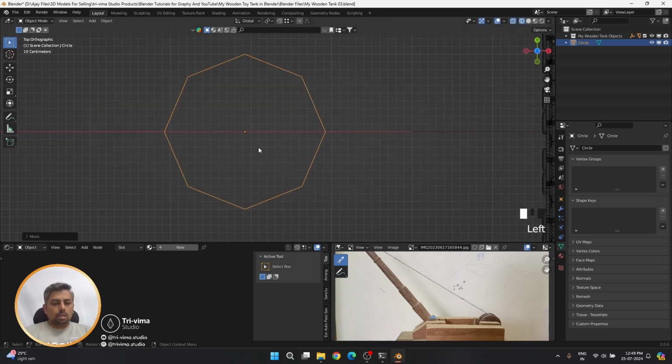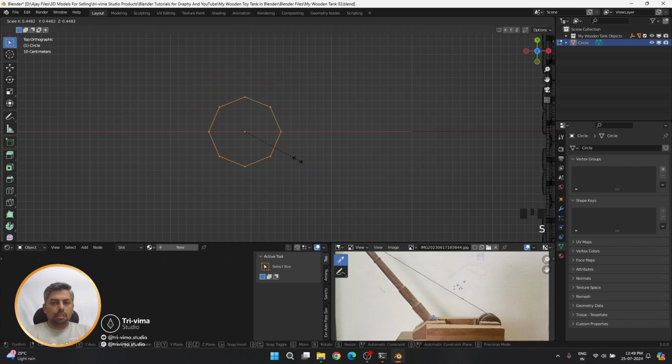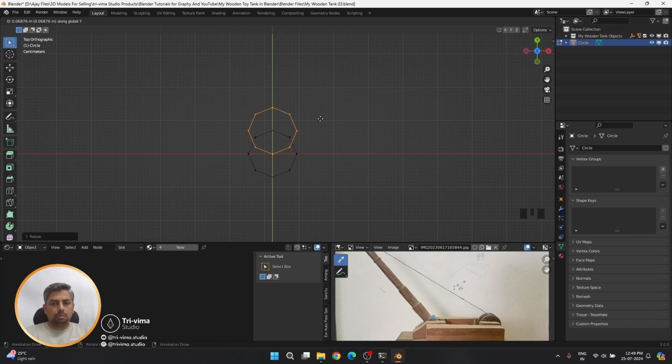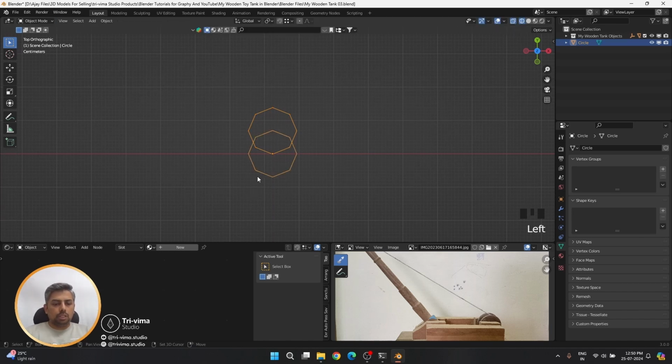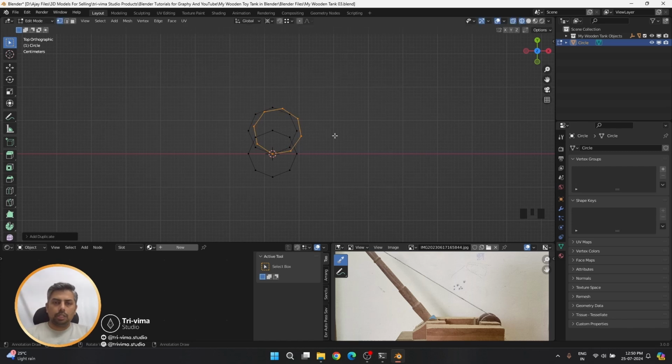We'll select it, go to edit mode, go to vertex mode, and scale this first, for basic. Then I'll create a duplicate and move it here. Now set this origin to here, come back to edit mode, and set it to 3D cursor. Now shift D, R, 120. You see this? Shift D, R, set 120. Then again shift R for this.